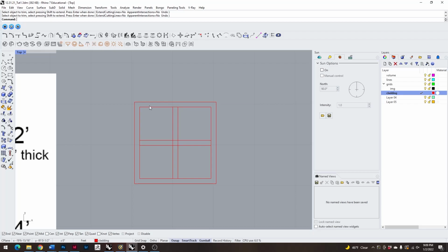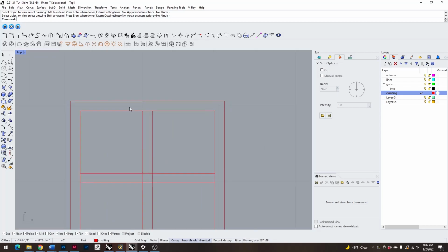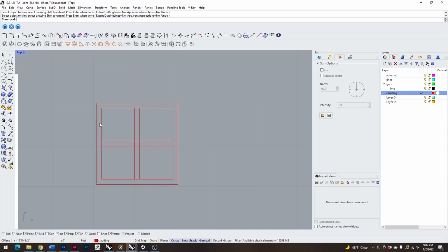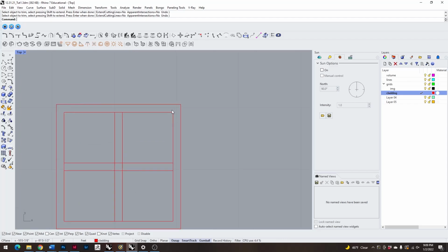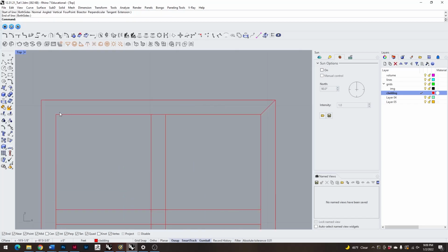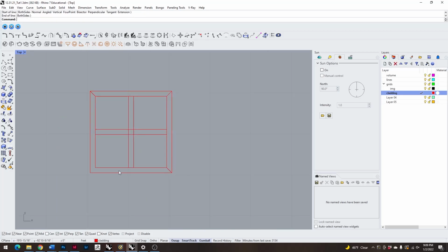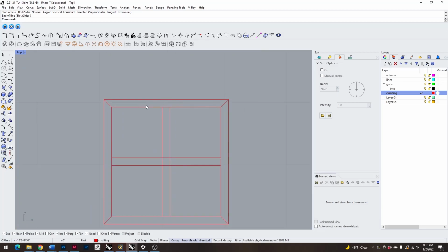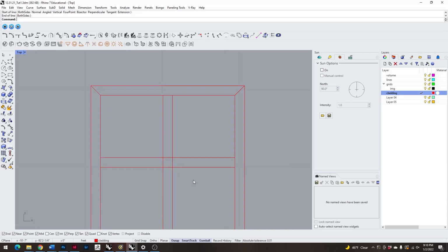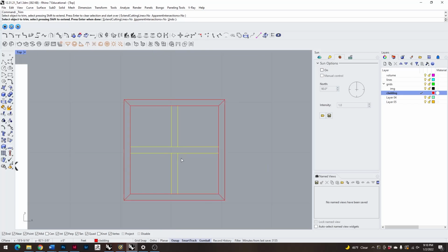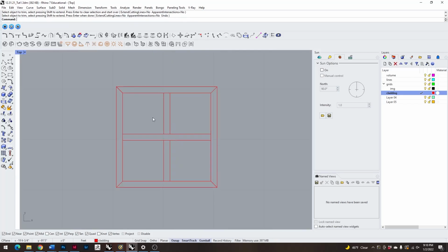One thing that you want to keep in mind as you're drawing these curves is that we're attempting to describe something built out of wood. So what we're using is linear elements. So things such as a frame, like this, a 4-sided box, would be composed of 4 linear elements joined together. And so I'm going to draw in a miter joint like this between that, such that this is a single piece of wood, as is this, as is this, as is this, and together they make that frame. And then here, I'm just going to trim away that piece to create my frame.